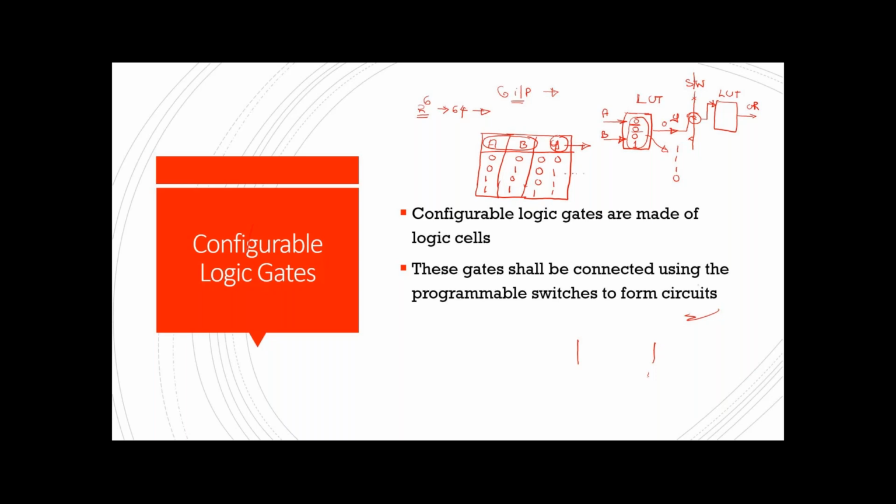Even for the ASIC flow, whatever RTL the front end team has written, if they want to test how the functionality is going to work, it will be tested on the FPGA itself. There is no other way. You cannot say you will test your RTL or functionality once you get the final product. That is not going to happen. If there is any mistake in the final product, you have to refabricate everything. But an FPGA is reconfigurable. If you make any mistakes, you keep updating and modifying it.